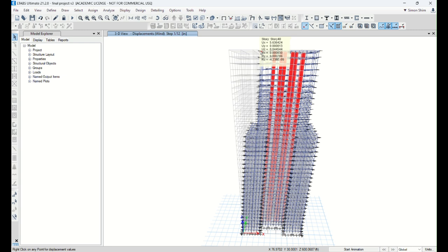Whether you made a mistake or not, you can just take a look at the displacement, X and Y. Also, you can see that your displacement is 5.6 inches. Sometimes if you made a mistake and end up with 100 inches or feet, obviously you should know you made a mistake, right? So this is kind of common sense. You are building engineering common sense by running all different types of buildings and exercises. You have to build a structural sense.